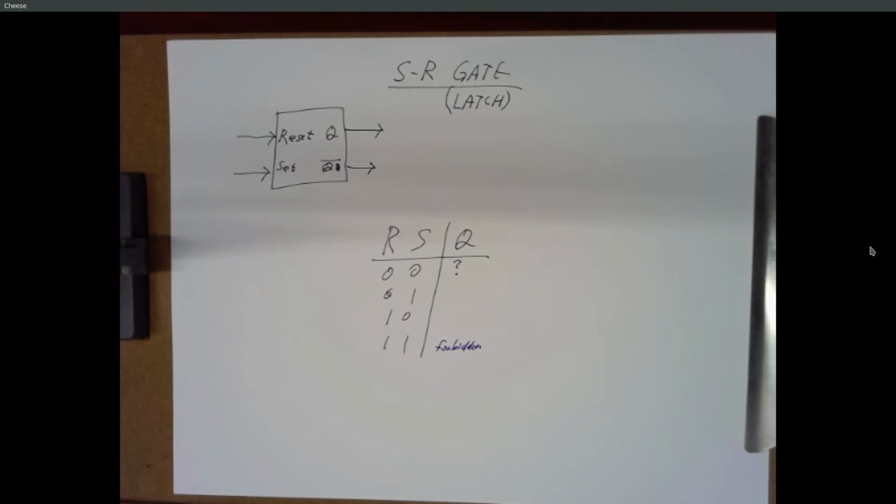Yeah, the very beginning. In the very beginning, it's unknown, right? But there's going to be some voltage level, and it's going to output something. If it starts off outputting a 0 and a 0, that 0, 0 is going to force us to output a 1, and then the 1, 0 is going to change that, right? So it will stabilize to something to begin with. But we can't really predict what it's going to be.